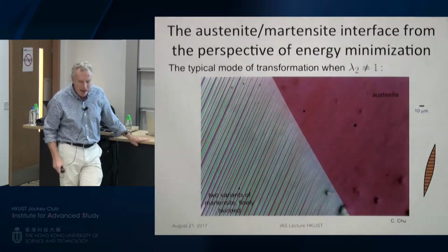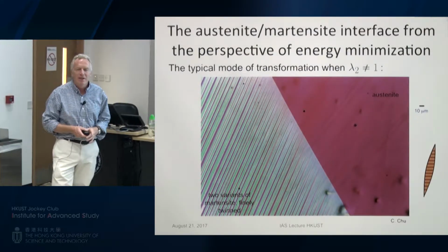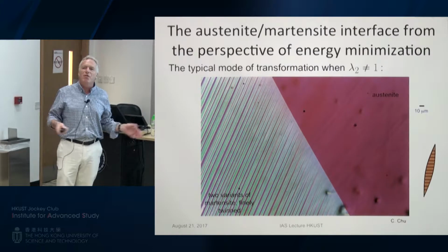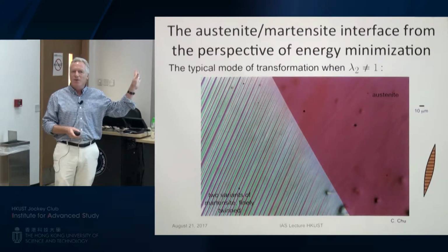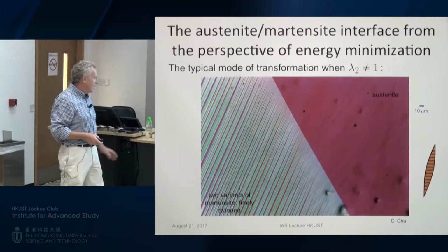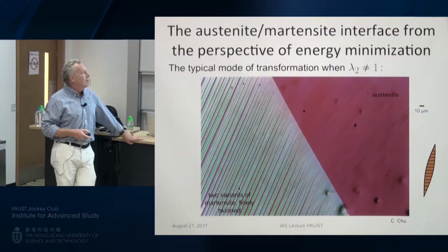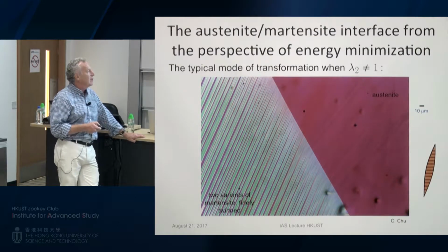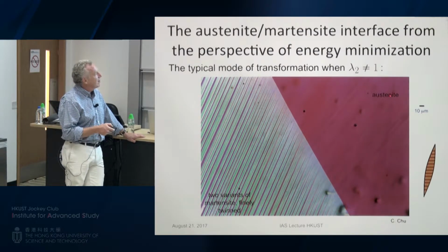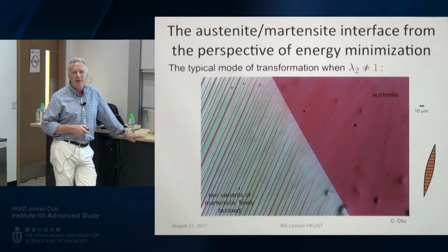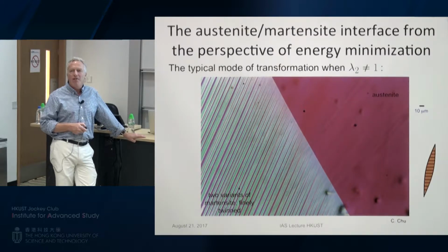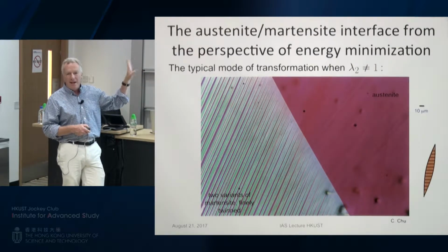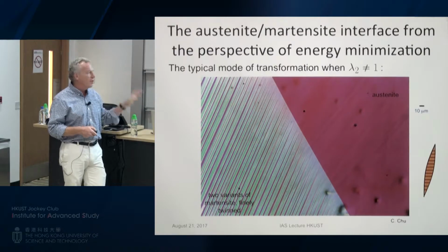Now, when we have a phase transformation in a martensitic material, but it actually applies to a great many materials that have reversible phase transformations, not like the tin I showed you, but many other cases, you'll see some different examples later, but nearly all reversible phase transformations, if you look at the finest level at the interface between austenite and martensite, you will see this. And this is the great simplifying feature of phase transformations, this particular structure. This structure is quite relevant to many transformation properties.